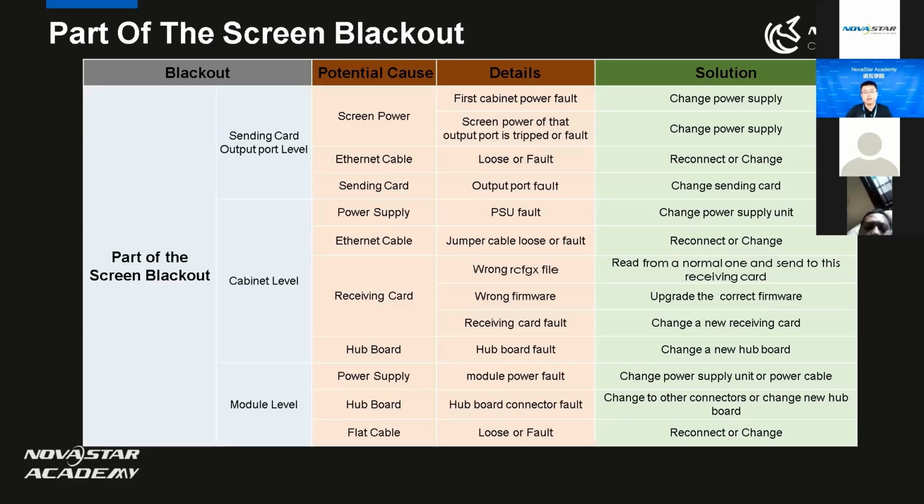And there is also flat cable, ribbon cable. So try to reconnect or replace the ribbon cable. So all these factors could be the possible reason for the part of the screen blackout.